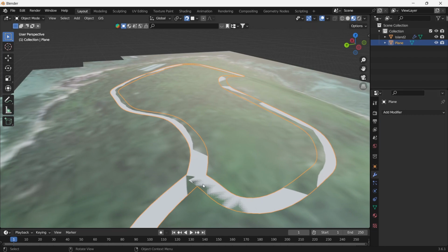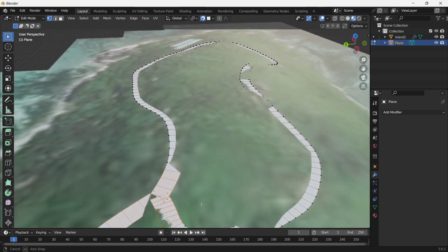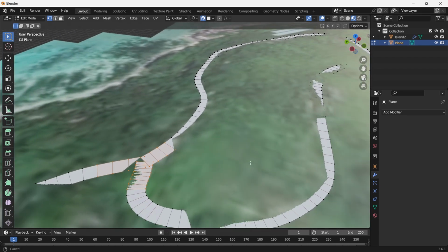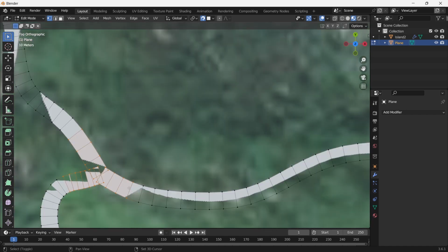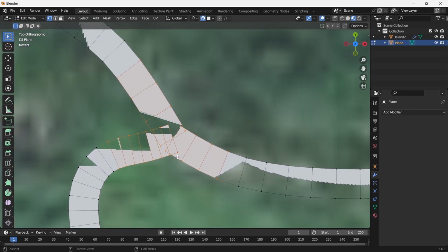As you can see, we have 3 loose ends at the junction. All we have to do is join the free ends manually. It is better to turn off snapping during this step, to prevent the vertices from snapping to wrong places, while adjusting them.